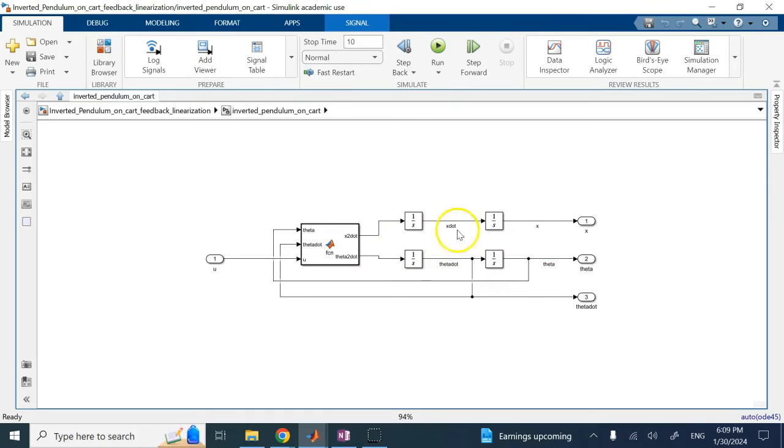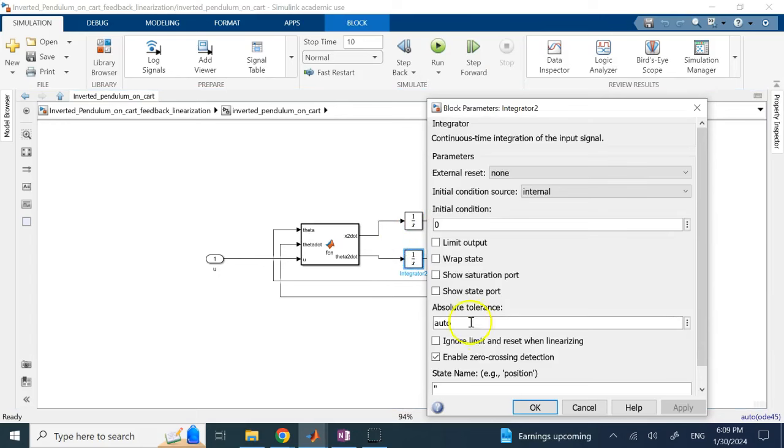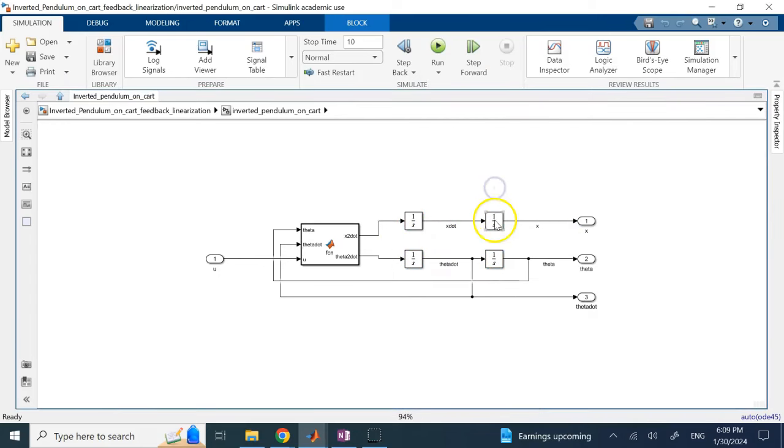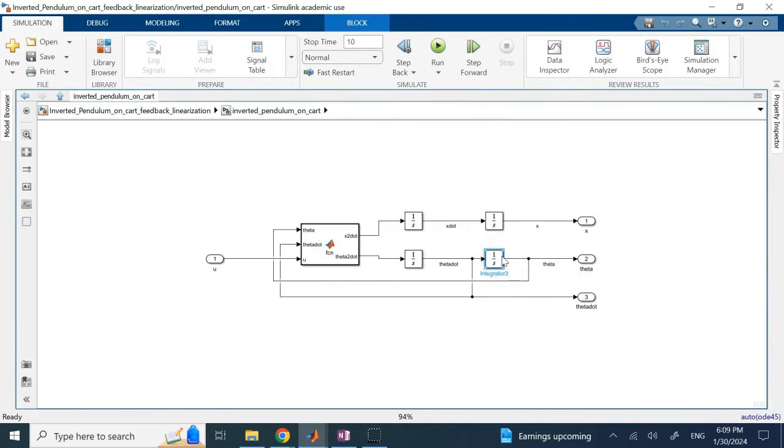The initial conditions for x dot and theta dot go here. Here I start at 0 velocity for both, so the system starts from rest and from position 0, but your initial angle is not 0. If you look here, I made it negative 60 degrees. Okay, this angle is so big that the linear control will not work on that.